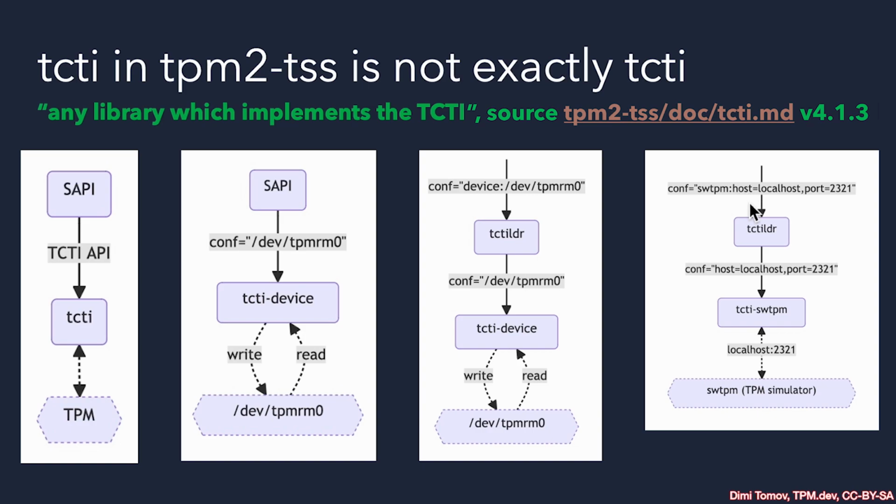So once we set this, the TCTI loader will load the proper TCTI-MSSIM library or TCTI-SWTPM library. Then it will pass that configuration string to that TCTI library, so it can actually send our command over a socket to the TPM simulator, and then we'll receive the response in the opposite direction. So let's take a closer look at the TCTI initialization.